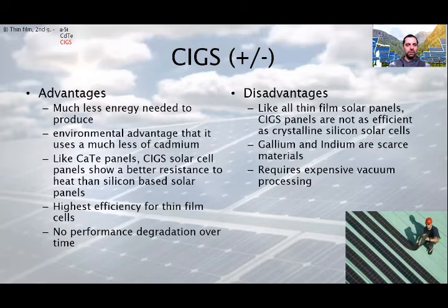The spectrum absorbed by mono, poly, or amorphous silicon cells ranges only from 400 to 700 nanometers, with the absorption range for CIGS cells being from 300 to 1300 nanometers. This means that the effective time for generating power is much longer each day for CIGS than other technologies. The electron power generating process keeps working from morning to sunset.